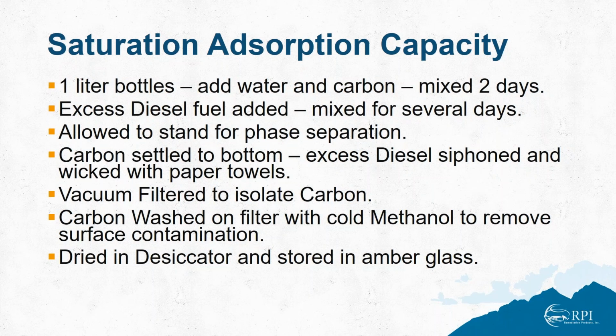And as we all know, there are rules of thumb out in the industry, and one of those rules of thumb is that activated carbon can absorb roughly 15 to 20% of its weight in organic materials, whatever those might be. That assumption has been used to essentially say, when it comes to LNAPL sites, that activated carbon doesn't have a role to play because you can't put enough of it in the ground. So let's just walk through the slide here so I can tell you how we went about this.